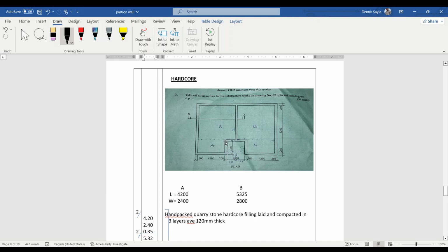Then this one, we have from here up to here is 4200. We have the thickness of the wall. So up to the outside here, up to this point here, we are at 4400. Then from this point up to this point is 2000, and then from 2000 we subtract the 150. So at this point we subtract 150 because we don't need the dimension of the wall.